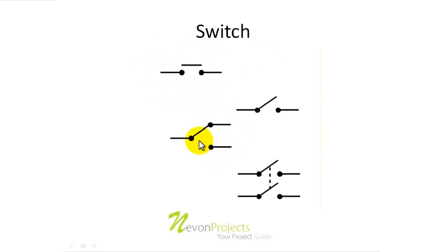Here we have a switch that can connect to two other ports. So if we want the input to be given to this section, we can connect this over here as a closed switch, and either way we can connect this switch towards this so that this connection will be made and this pin will be open. Now similarly we have double pole double throw, where by a single press we can make and break two connections at a time.